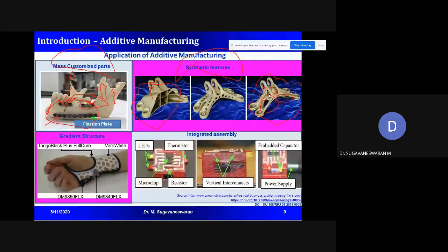If you look into the last diagram, you have a lot of non-linear curves, a lot of non-linear surface, which is very difficult to manufacture. That is the reason why engineers are not comfortable using topology optimization, because the issue is manufacturing constraint. This is very easy to manufacture, though the weight is higher than that of the last design. It is simple to manufacture, but the last can also withstand the same strength with less material. The only difference is it has a lot of non-linear features which are difficult to manufacture.